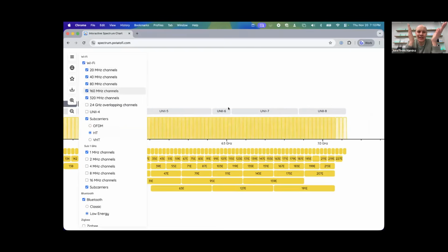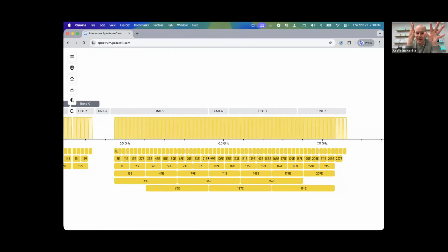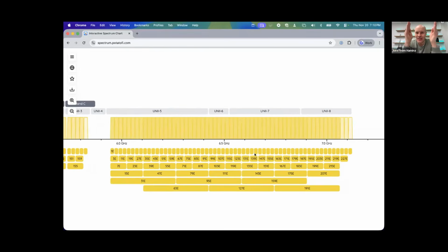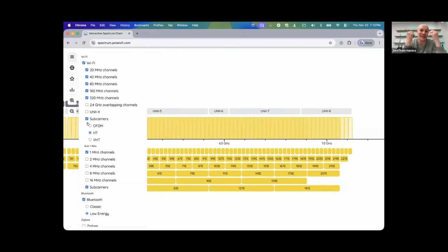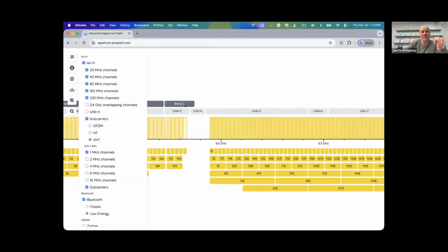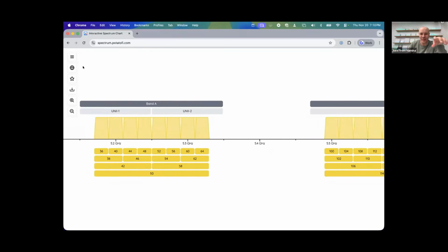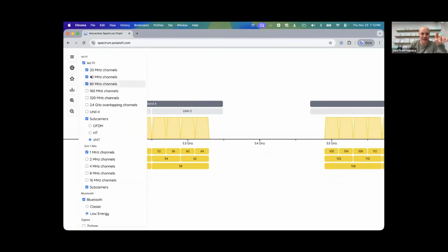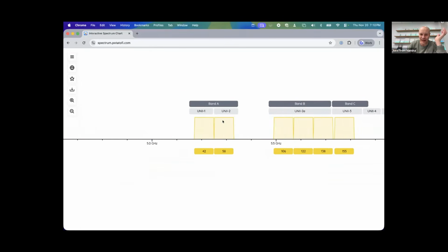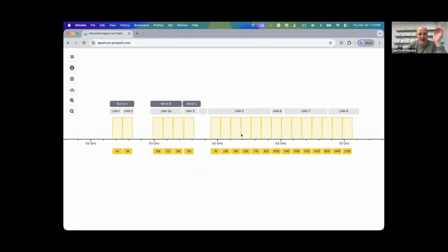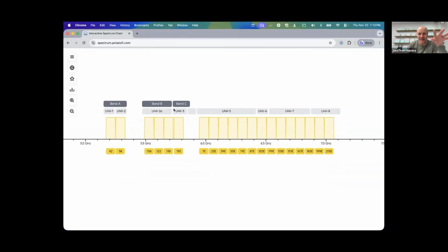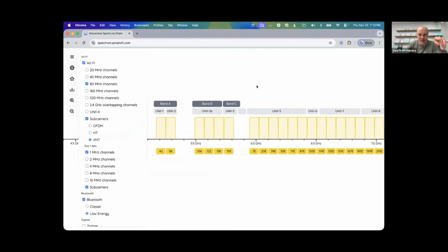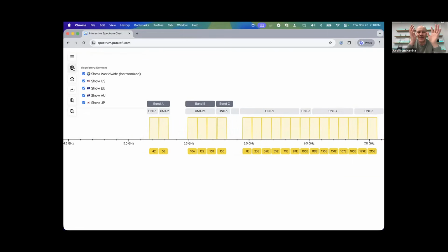Yeah, essentially, it is double the data rate. If you double the channel width, it's double the data rate, and typically even double the throughput, assuming certain things. But if we look at 80 megahertz, which would give really good data rates, and we compare America settings and EU, this is where we can see how many of these 80 megahertz channels we lose as you take out the US.